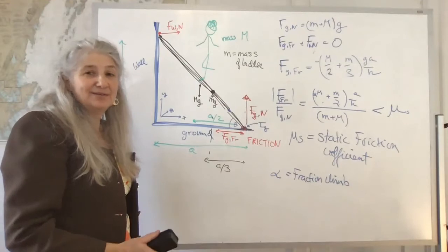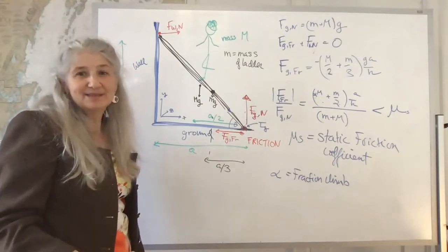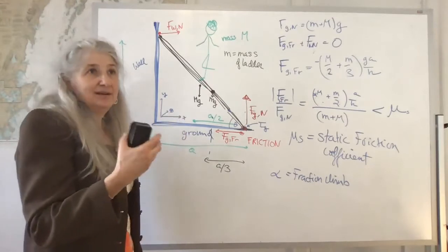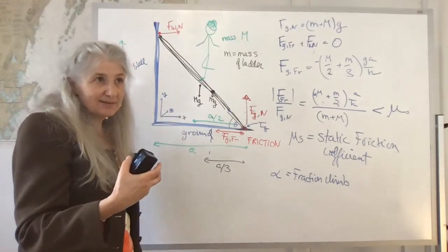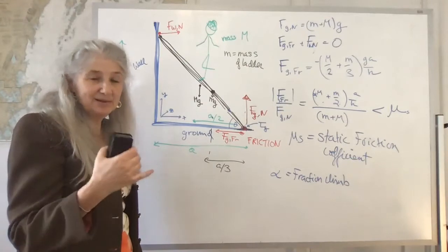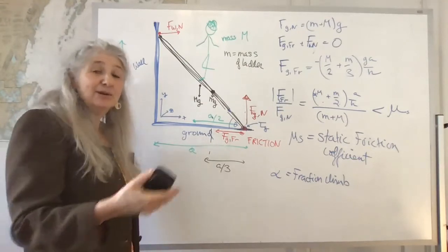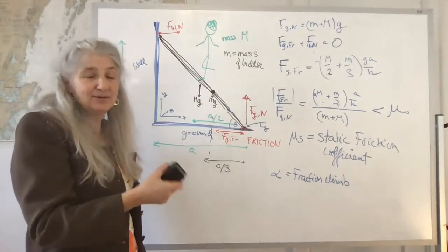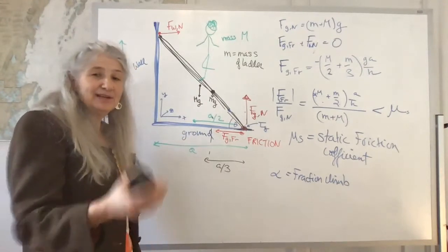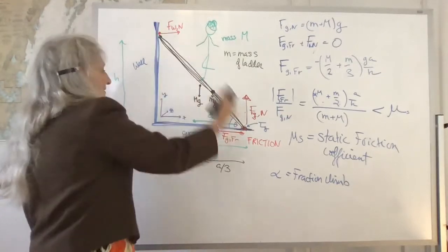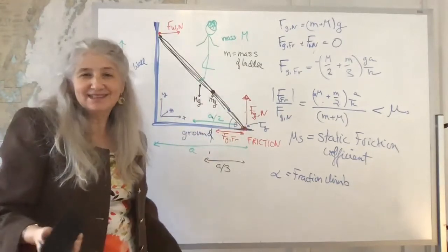So when you're doing these problems, for here we had two equations for static force balance, and then we used one torque, so three equations, three unknowns. We could have written down a fourth equation and it would have been redundant, but when you write down the fourth equation, computing torque around, say, this point instead of that point, sometimes it's easier to solve.